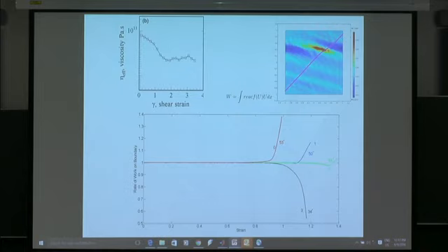So what I did actually is I integrated, we call it essentially the force that needs to be exerted on the boundary times the velocity. So in other words, the work that's being put into the system. Okay, and I checked that is in fact equal to the volume work going on inside. Okay, just as a check.